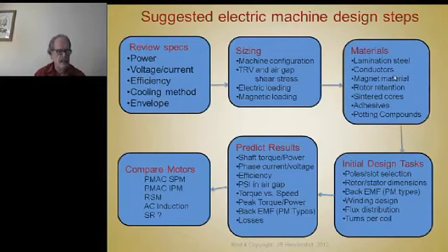The permanent magnet AC motors, or brushless motors driven by sine drives, can be surface mount or interior. Now this is very common: you've been told that you have to design a permanent magnet synchronous machine, but do a design comparison on an IPM or an SPM and tell me which one is best for us from a cost and performance point of view. And frequently you have to work with your inverter engineer on this as well. And other times people ask, can I replace our existing motor with an SR, an induction motor, or a reluctance synchronous machine, RSM?